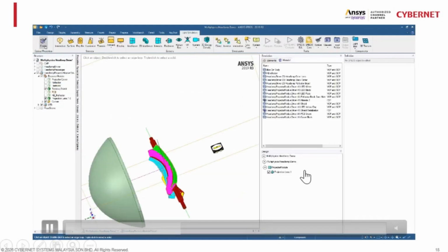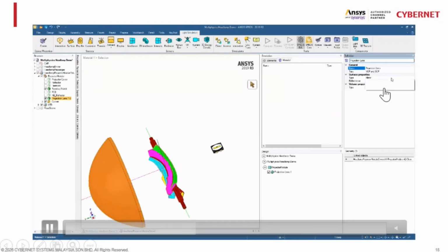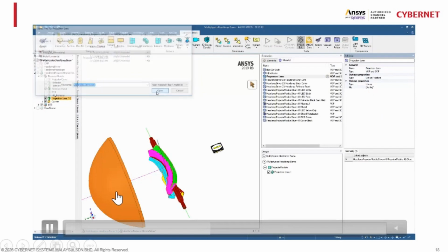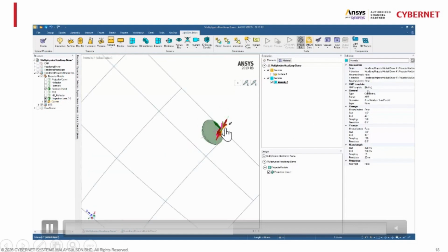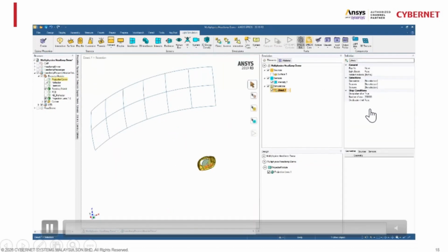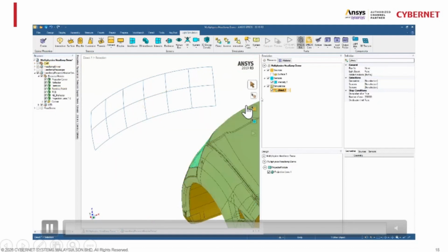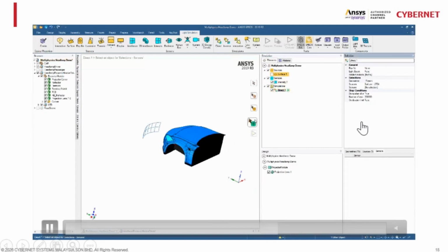Okay. Now we need to set up the material for all these parts. For example, for the lenses, we set this material, which is the transparent PMMA, to these projector lenses. Next, you input the intensity sensor. We do the same: we need to set the coordinate for this sensor. After that, we need to set up the SMP template, which is the standard we use. You can assign the standard directly to the sensor, so after you do the simulation, you can directly see what is passed and what is not passed according to the standard.